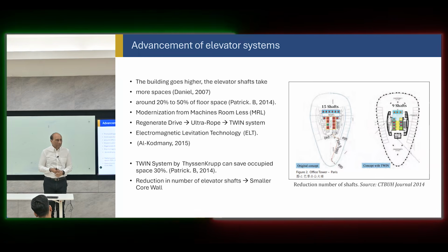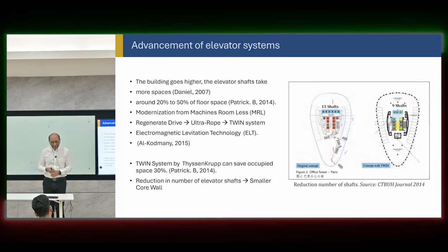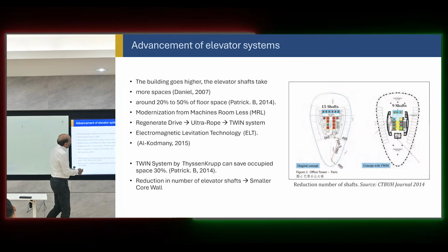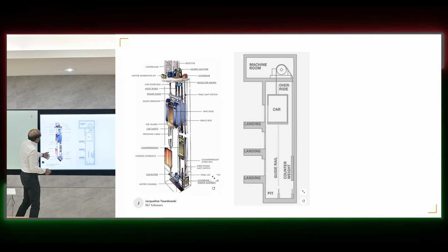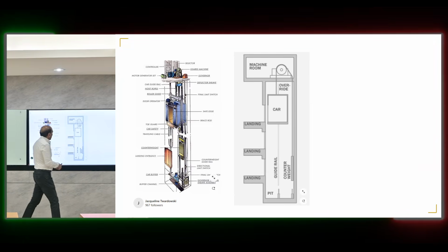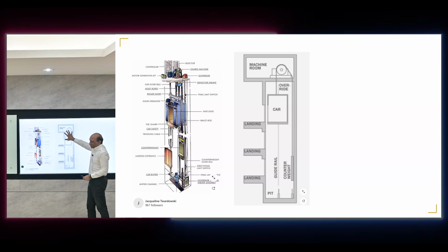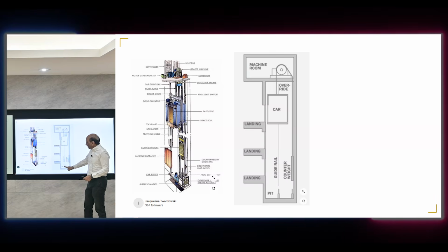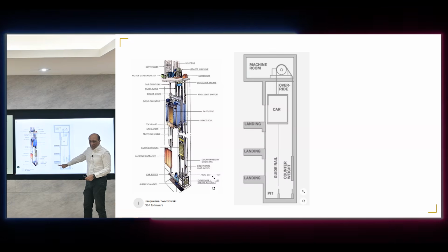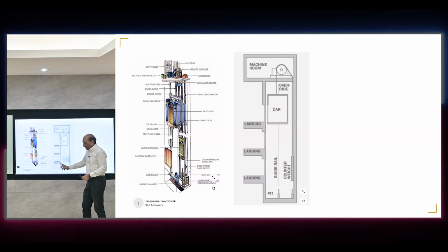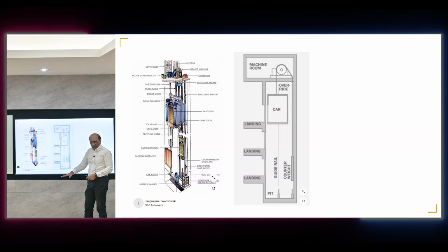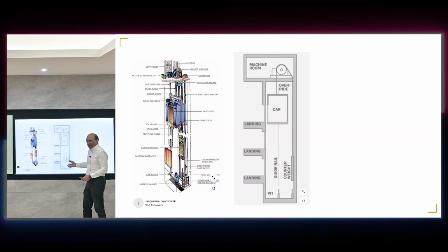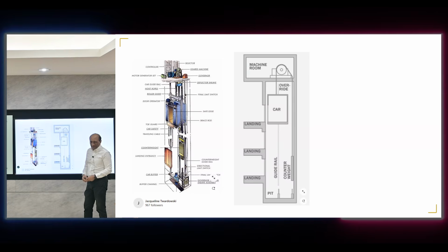As the elevator technology becomes better, the number of cores reduces, and then we have to find some other ways to support the lateral loads. And now they're looking at, so this is just the way a typical elevator will work. You should know that for a typical elevator, there are 3 things that we need to know. One is this pit, which is needed below the last floor. And this causes problems with the foundation raft, because normally there's a floor raft here, foundation, but this pit has to go into the base, into the foundation raft, and then you need a separate arrangement to capture this one. So this creates a design complication in the design of the foundation raft and the piling system.